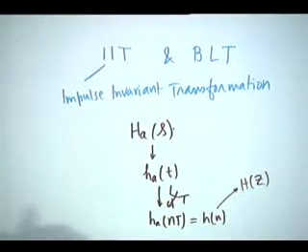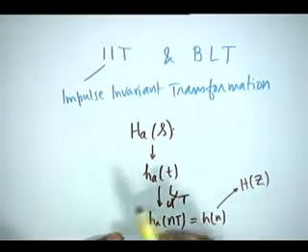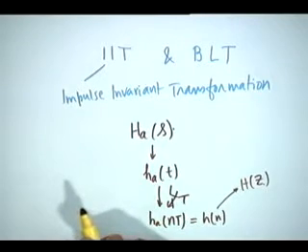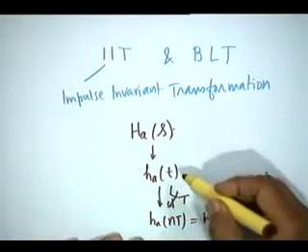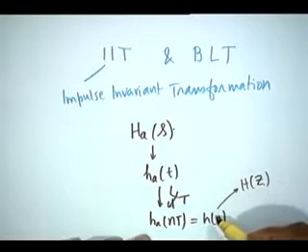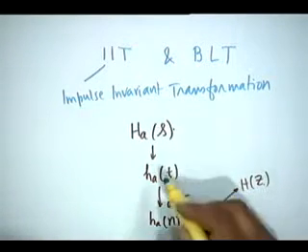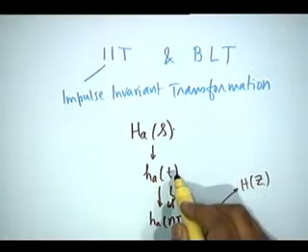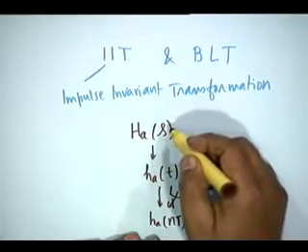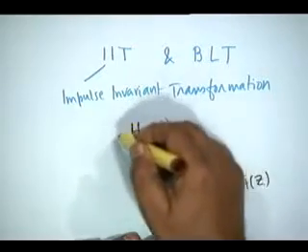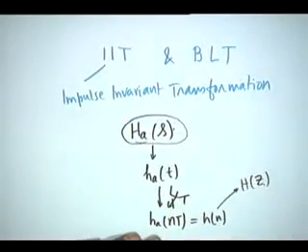This is why aliasing occurs, because no transfer function in practice is band limited. If you want to respect the sampling theorem, the sampling frequency must be greater than or equal to twice the highest frequency at which H_a(s) is non-zero.